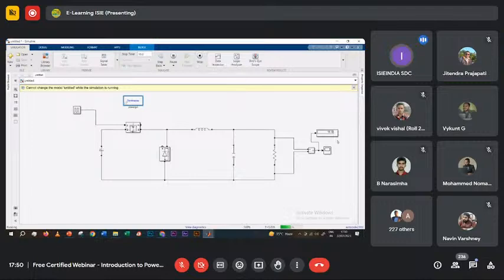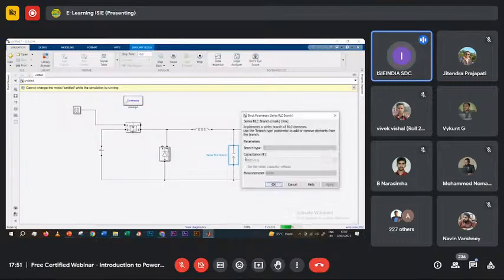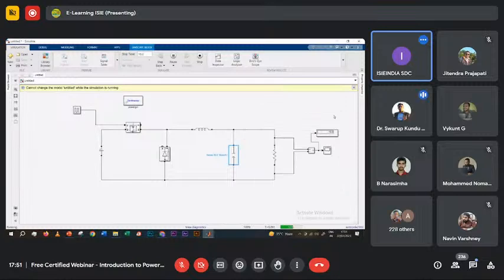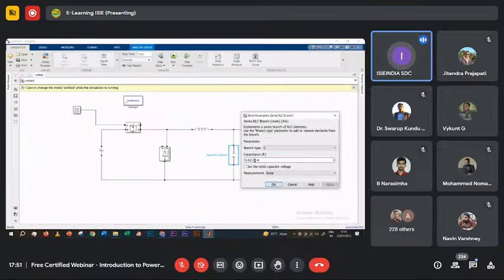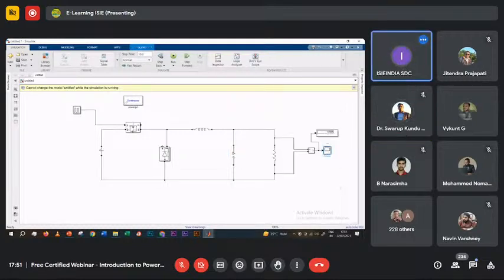Yeah, so I'm getting some error. So kindly check the value of capacitance. I think it is wrong. It will be picofarad, let's try. It is of the order of picofarad when I calculate it. So basically, I think the capacitor value I have inserted is wrong. So kindly do the calculation again so that we can get the right answer. E minus 12, can you try? It's showing a minus curve because of this error.